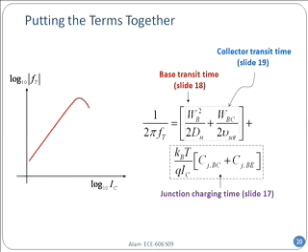As a result, when you begin to increase the collector current, I sub C, let's say you're increasing it, the second term begins to drop because you can charge the capacitance fast. You have a lot of current flow. So you can charge the capacitance first, and so the second term begins to go small, and your 1 over f_T becomes gradually smaller, f_T becomes larger. So you can see the frequency is gradually increasing as you make the collector current more.